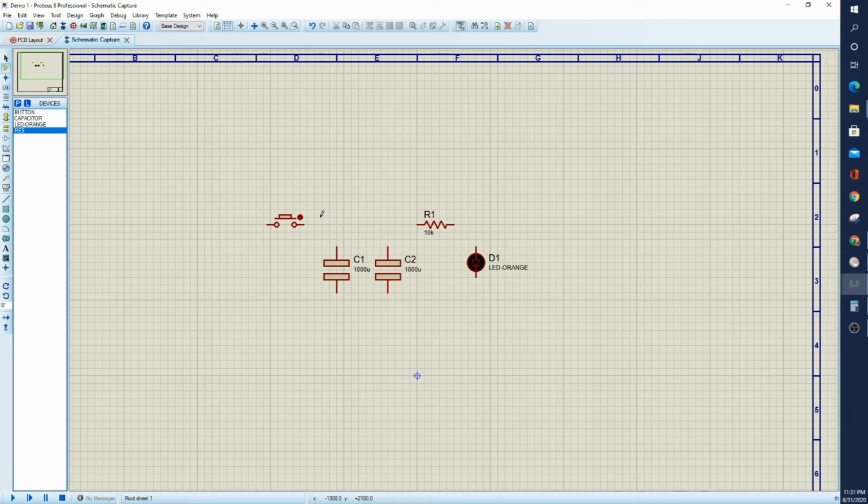And so you'll notice that my little pencil here, when I hover over one of the endpoints, one of the terminals, it turns green, and it highlights the node. And so if I left click, I can pick a beginning and an end point. And so how do I join this connector to this terminal up, or to this wire up here? Well, again, I can select a terminal and come up and then click on the wire.